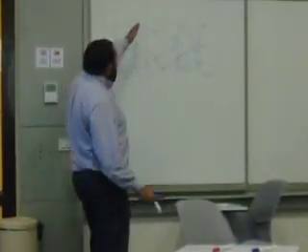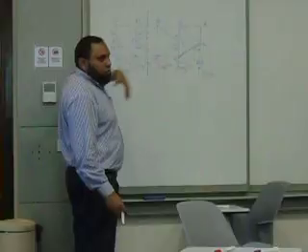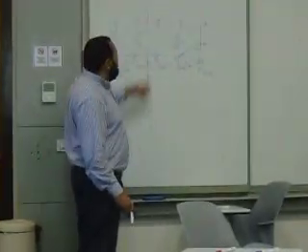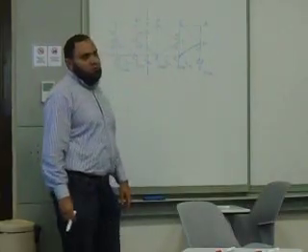So this is our K-truss. I'm expecting the maximum to be in the middle, so I want to get the ones in the middle. But if I'm taking a cut here, I'm cutting through four members. So how can I solve it?